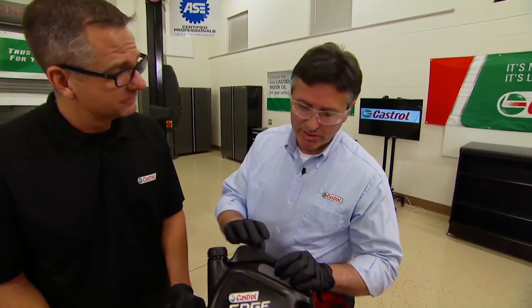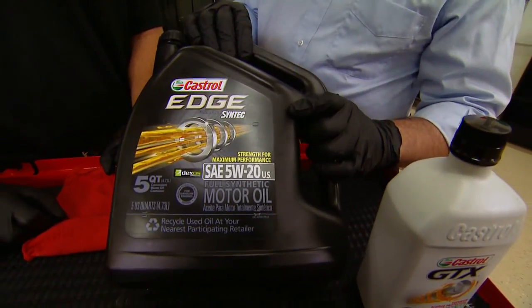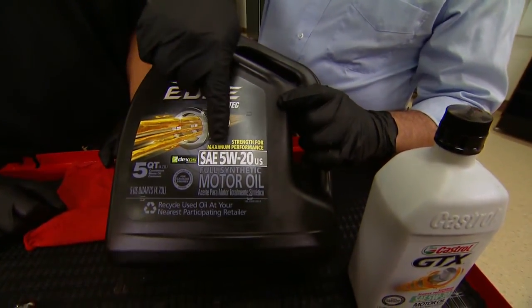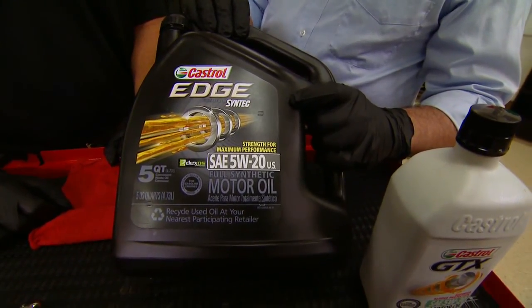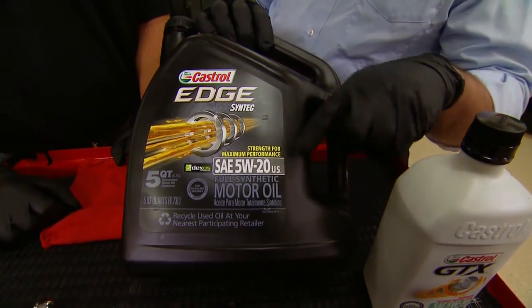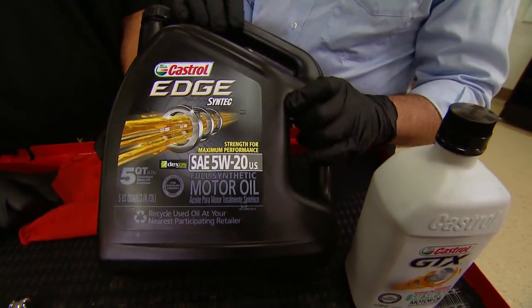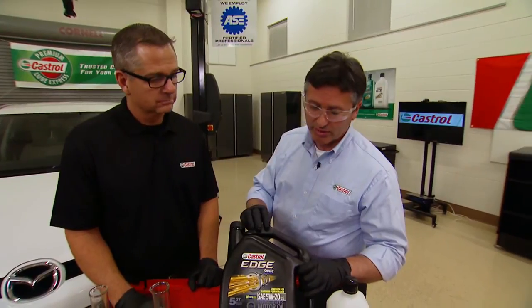Now with oil types comes viscosity ratings. Tim, what can you tell our professionals about viscosity ratings? John, the viscosity ratings that we see on the bottles are examples. This is an example of a multi-viscosity engine oil rating. The first number that ends with a W is the winter viscosity rating. That's the ability of the oil to flow and protect properly under cold conditions. The second number that we see is the high temperature number, and that's the ability of the oil to provide correct viscosity at high temperature to protect the bearings inside the engine.